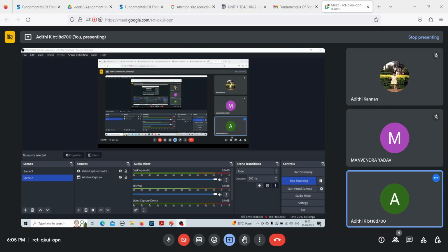So if you substitute E as Wi, the work index notation, that is applicable when Xf is infinity. That is, the size of your feed is infinity and size of the product is 100 micrometer. So if you substitute Xf as infinity, this entire term will go to 0. And if you substitute Xp as 100 micrometer, then your E will be equal to Wi.